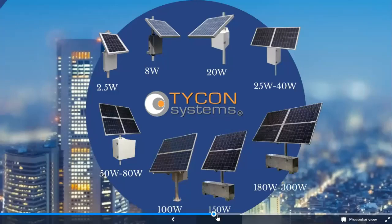So each is designed with your specs in mind to not over design, and definitely not under design, but find the appropriate system with a buffer so that if you do have some cloudy weather, or maybe there's dust on the panels, or maybe the tilt is off, there is a bit of a buffer built into this. And so we have 2.5 watts draw all the way up to 300 watts continuous. And you can see the panel size and array based on how much draw is needed.